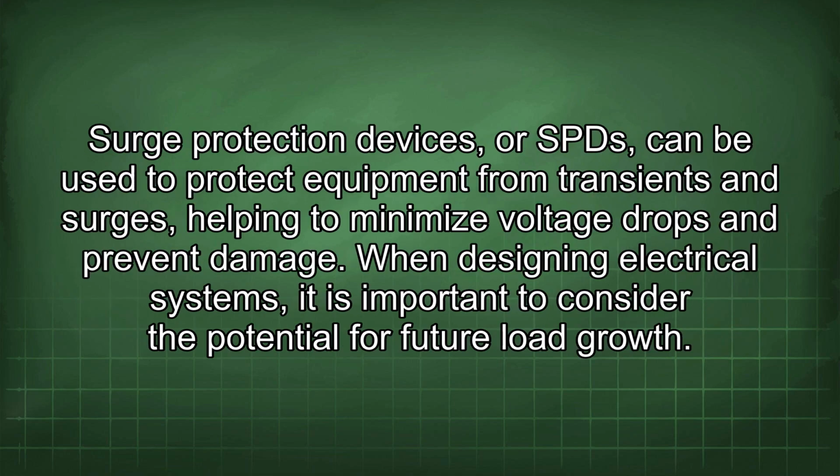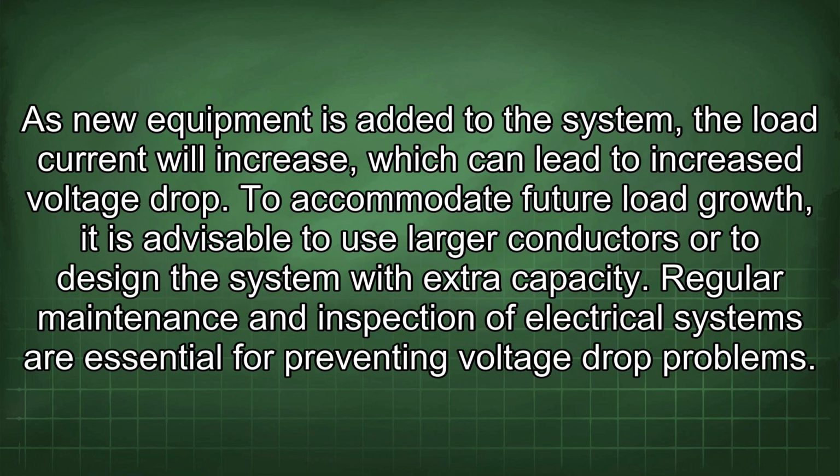Surge protection devices, or SPDs, can be used to protect equipment from transients and surges, helping to minimize voltage drops and prevent damage. When designing electrical systems, it is important to consider the potential for future load growth. As new equipment is added to the system, the load current will increase, which can lead to increased voltage drop. To accommodate future load growth, it is advisable to use larger conductors or to design the system with extra capacity.